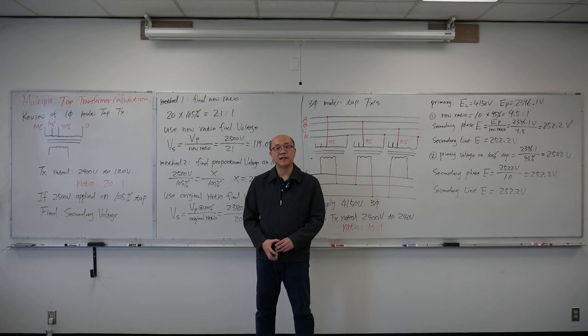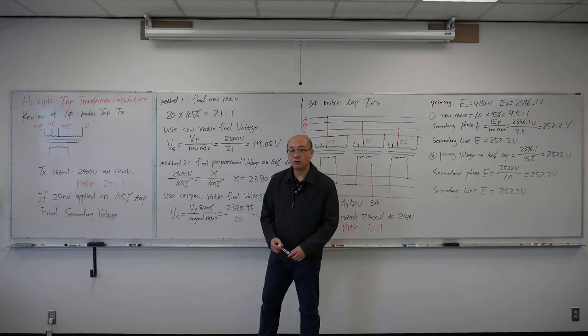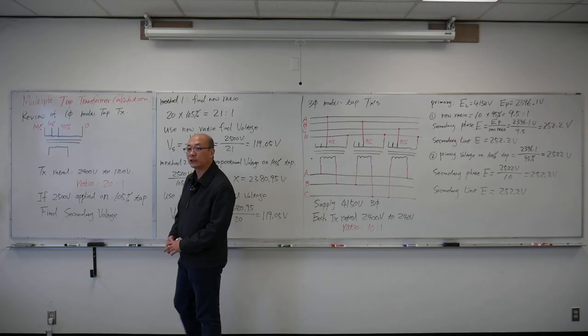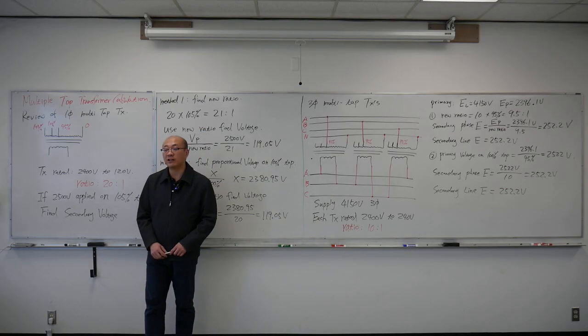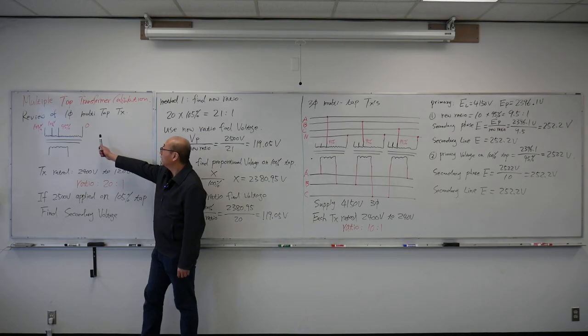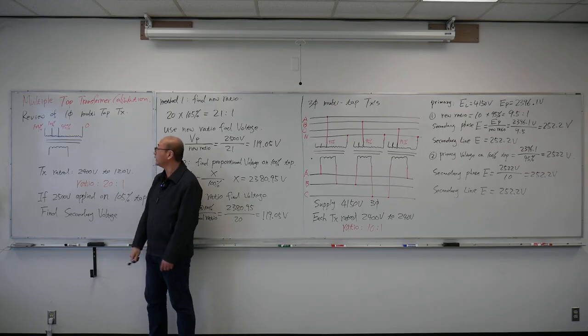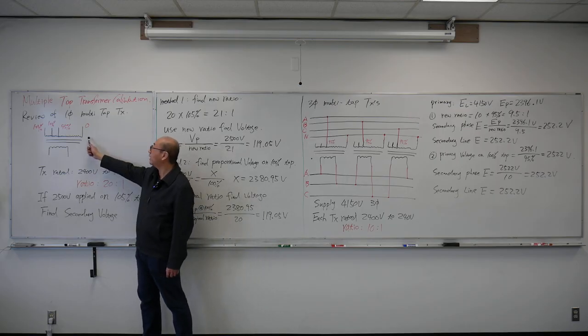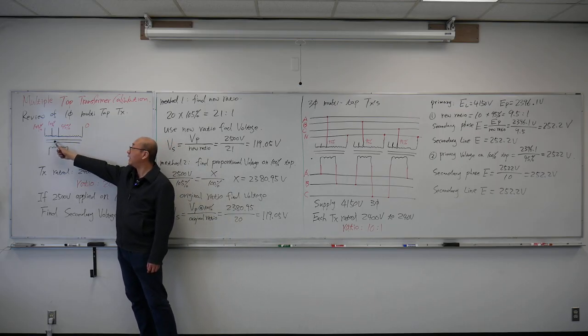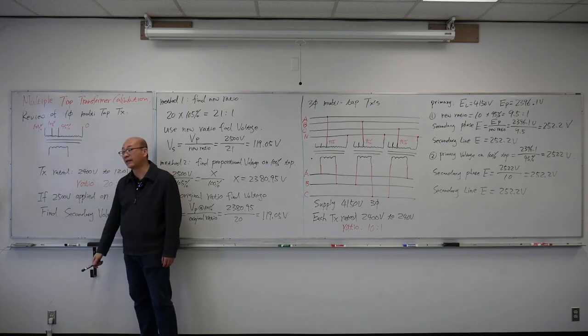Hello everyone, in this lesson we're going to talk about multi-tap transformer calculations. So we're going to review the single-phase multi-tap calculation first. Here's a multi-tap transformer. On the primary side, I have a 95% tap, 100% tap, and 105% tap.